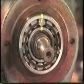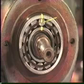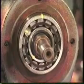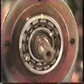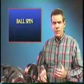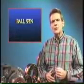A defect on a roller will also generate certain discrete frequencies, depending on how many times the roller turns over during one revolution of the shaft. With the reference marks in line again, we rotate the shaft one full turn and this time count the revolutions of the roller. 1, 2, and a fraction. This roller defect frequency, or ball spin frequency as it is commonly called, is also non-synchronous